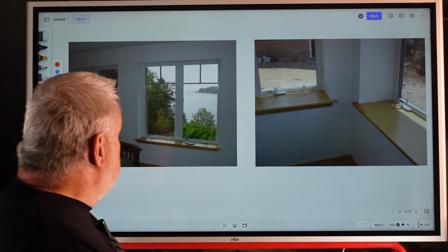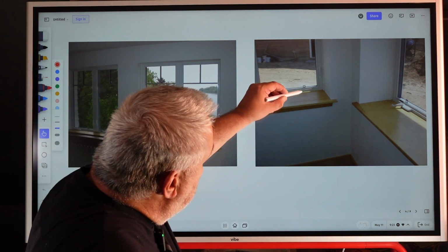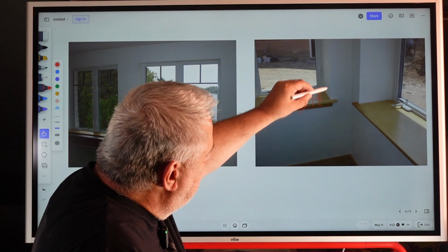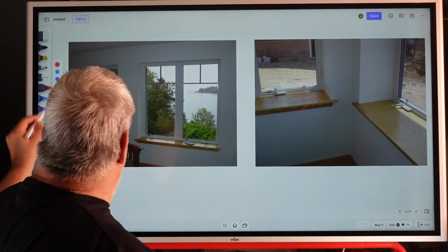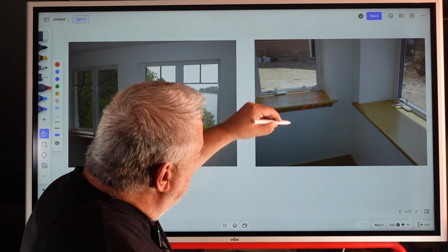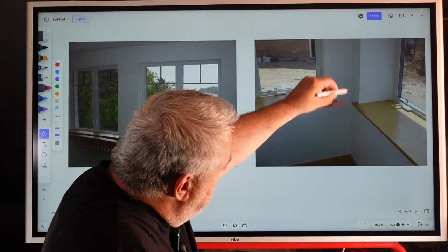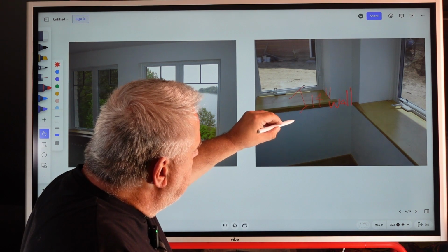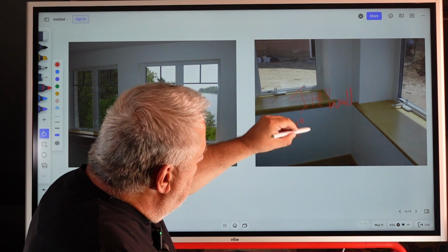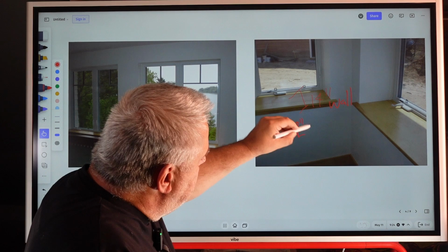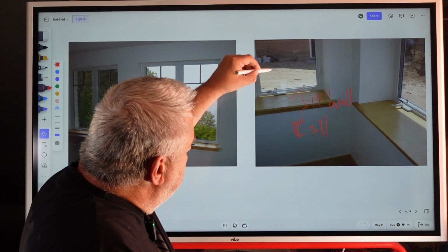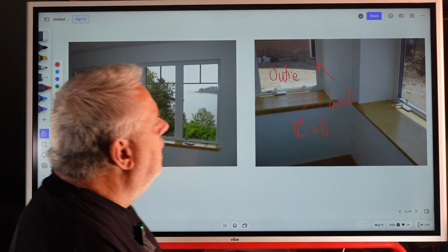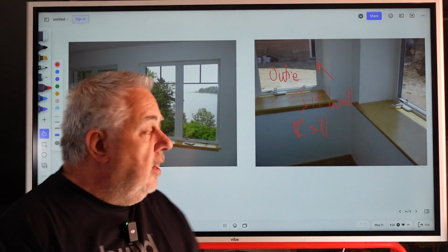So quick shot, this is just the interior. Notice we have 14-inch walls here, right? So 14-inch walls, those are probably yielding not a 14-inch sill. That's the wall. The sill, if I had to guess, is probably somewhere on 11 inches. Well, we have a little overhang there. We'll call it 12 inches, 12-inch sill. And this, of course, is the outie, right? It's pushed all the way back to the outside plane of the wall.